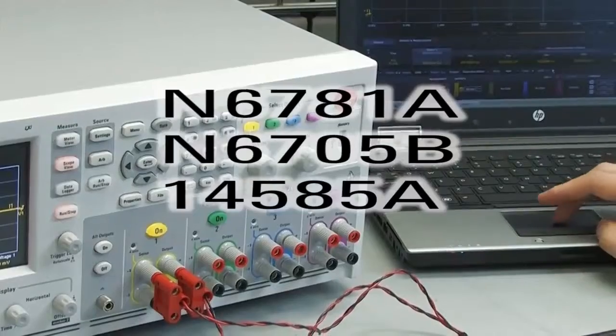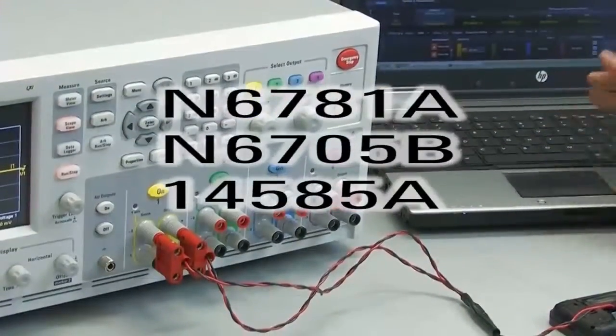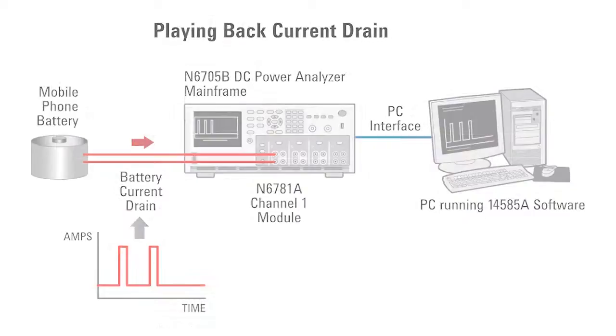The captured current profile was a 2 amp peak load with a 0.3 amp average current drain. The captured profile was then played back as a dynamic current load over an extended period to discharge a battery to its low voltage cutoff point. This setup can be used to evaluate multiple batteries with assurance that the results are truly comparable.